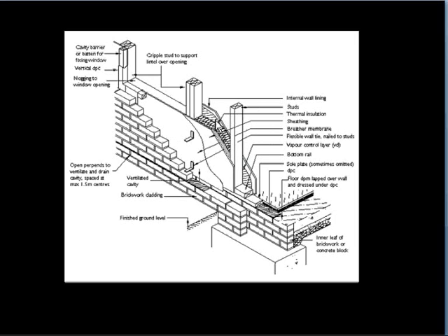If we want to prevent the ingress of rainwater, on the outside of the cladding system we've got a breather paper which is waterproof but lets water vapour pass through. Where any of the structure might touch the outer leaf, because the outer leaf is going to be quite wet, we're going to wrap a damp proof membrane around any closures to the cavity and any battens for the window fixing around the cavity itself.